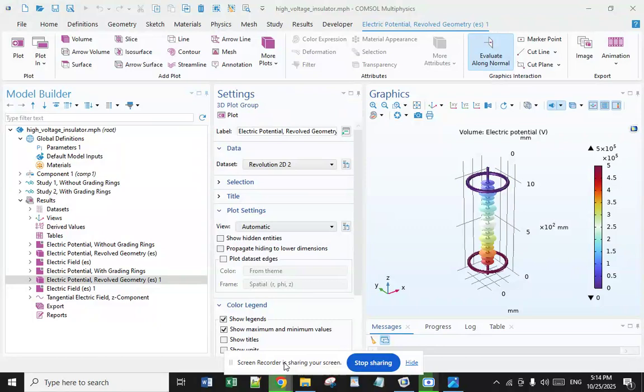The next is high voltage insulator design considerations. The choice of high voltage insulator type and design depends on several factors such as the line voltage, electrical conductor loading, environmental conditions, and tower design specifications. Some important high voltage insulator design considerations include, the first one, creepage distance. Creepage distance is the distance along the surface of the insulator required to prevent arcing. The creepage distance must be large enough to withstand the line voltage and prevent arcing.